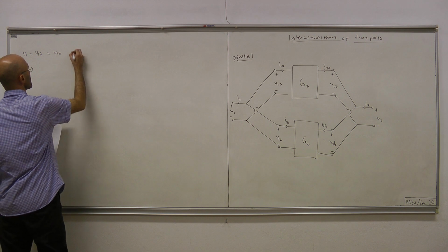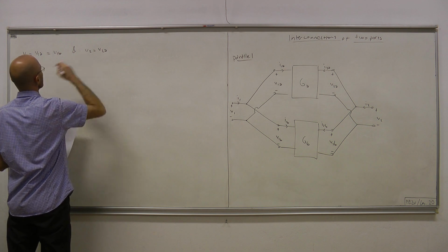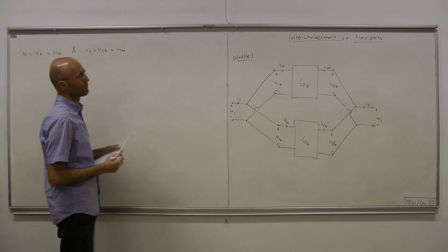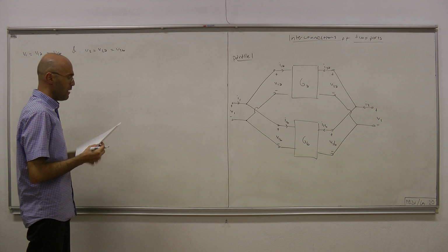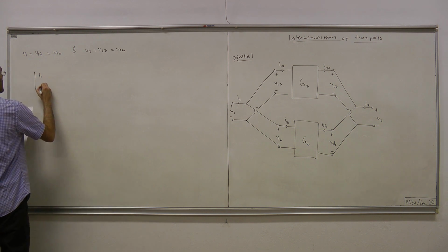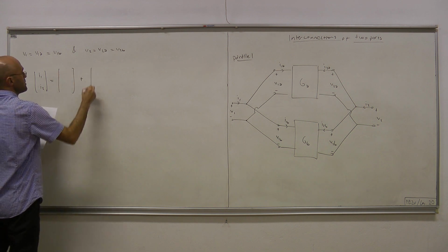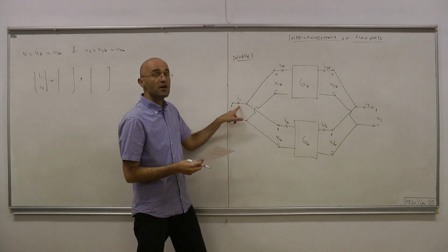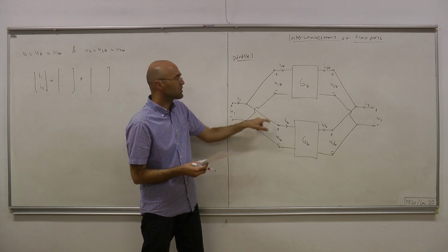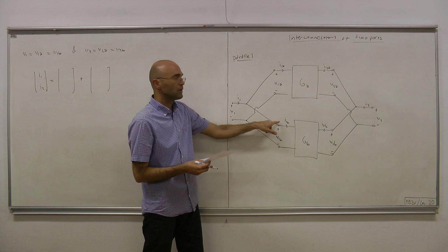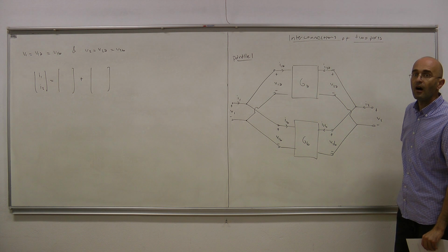And likewise, for the second port, V2 equals V2A, and that's V2B. Okay. This voltage equals this voltage, and also equals that voltage. How about currents? Okay. What we have is, now this current I1 equals this current plus that current by KCL. Now this current is I1A and this current is I1B. Therefore I1 equals I1A plus I1B. Likewise, I2 equals I2A plus I2B.